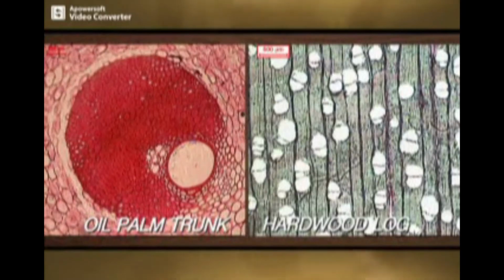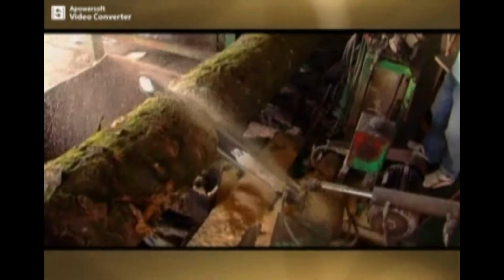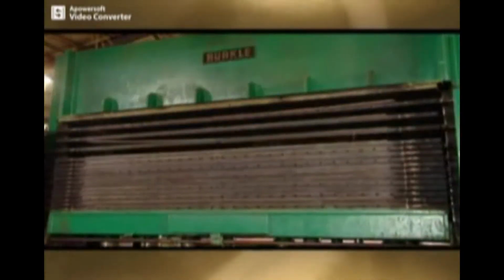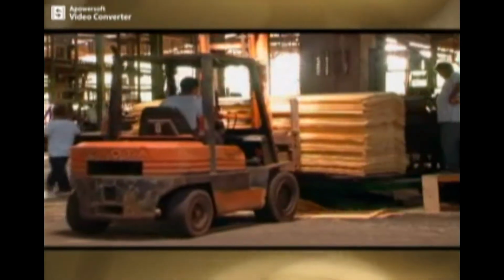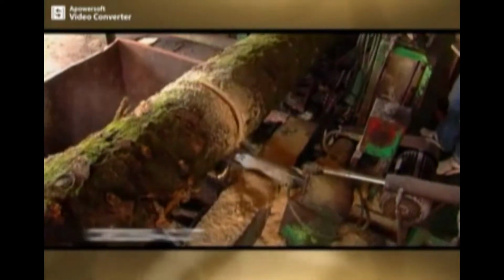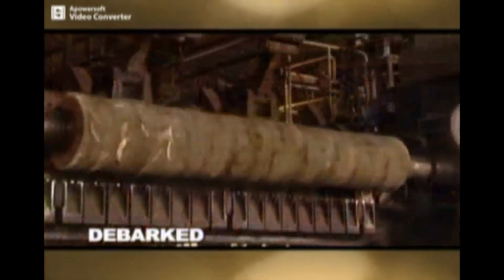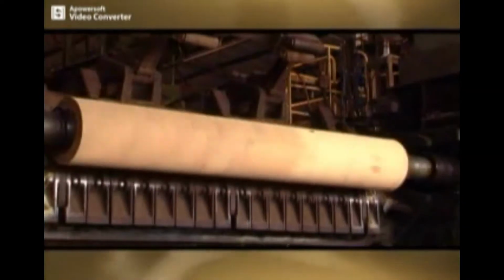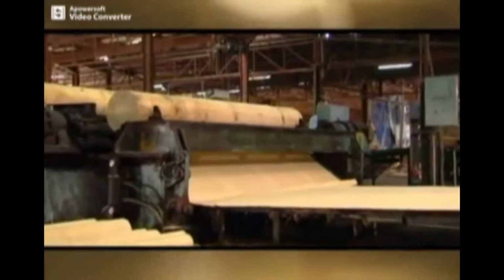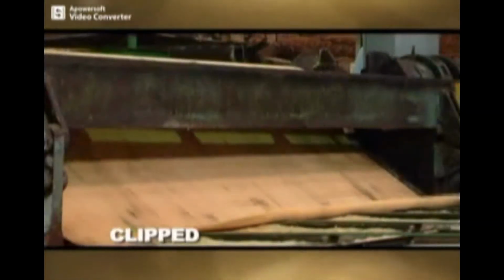The process of producing plywood using OPT is similar to, and not different from, producing plywood using hardwood logs or softwood logs. The main processes include veneering, drying, lamination and finishing, as can be seen in this short presentation. At the factory, the OPT is cross-cut to the required length. Then after, it is debarked and rounded up. The cylindrical block is then peeled into veneers and clipped to the required width.